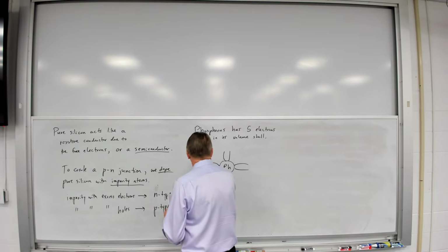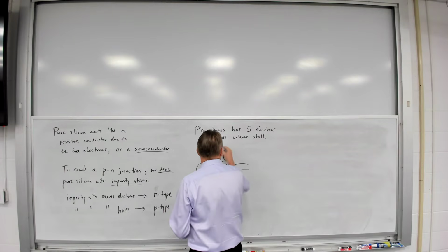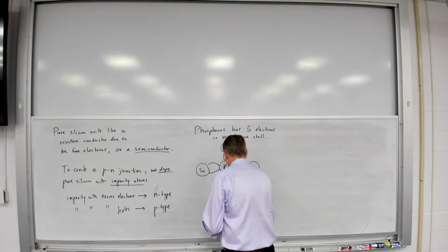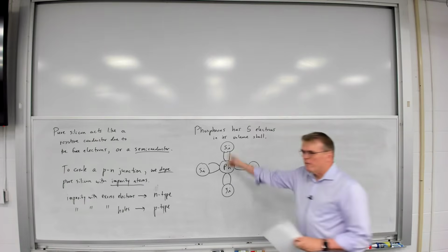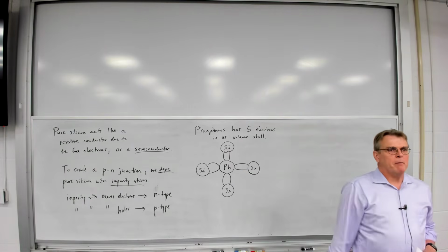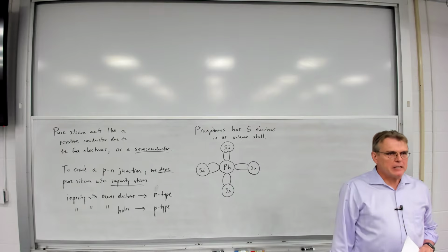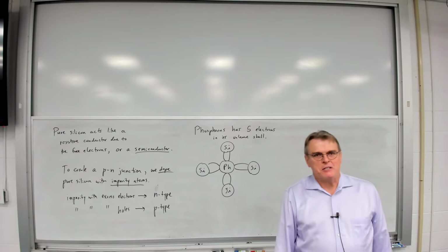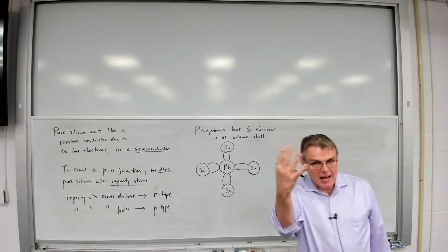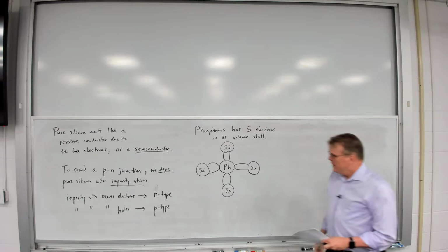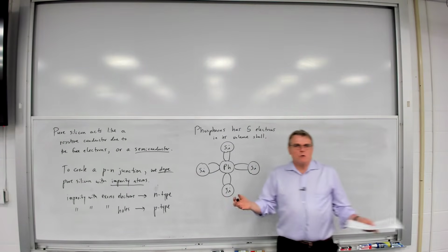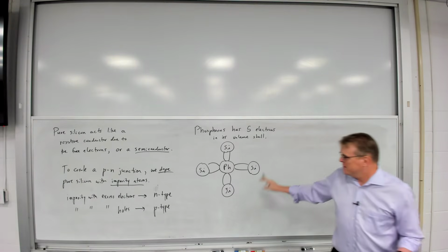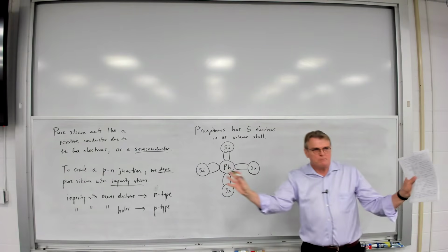It's going to replace one of those silicon atoms. And phosphorus will very happily form the same form of covalent bonds with the adjacent silicon atoms. But the problem is phosphorus has an extra electron it doesn't need to form those 4 covalent bonds. It has 5 electrons in its valence shell. So in this case, phosphorus is quite willing to give up that excess electron and doesn't want it back. Once it has 8 electrons in the outer valence shell, it's happy.